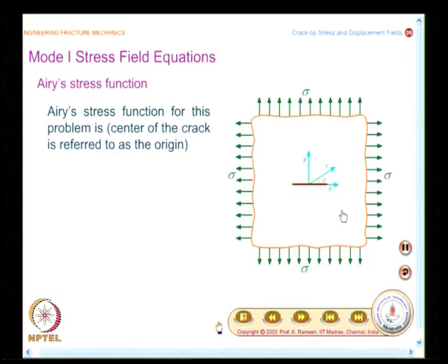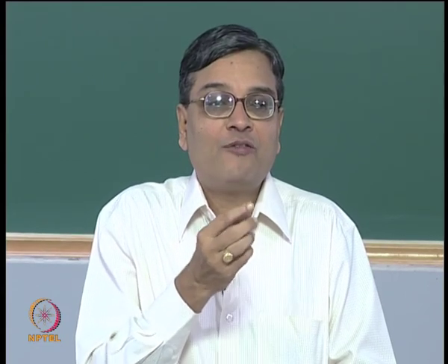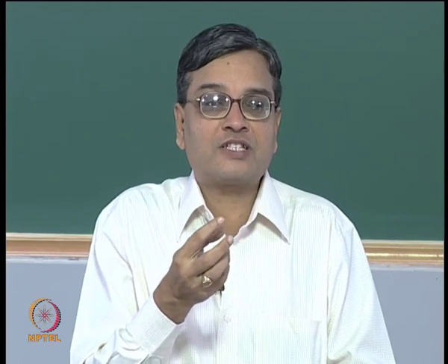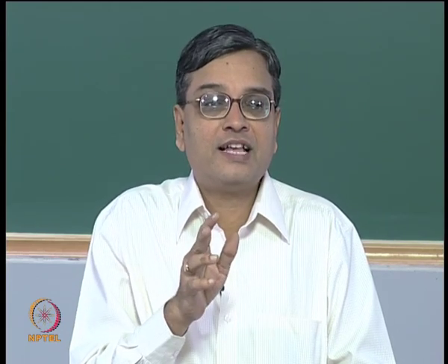But what you find here is that Westergaard has actually considered the problem of a central crack in biaxial loading. Just because people were accustomed to solving these problems for uniaxial loading, rightly or wrongly, whatever solution Westergaard provided, they simply used it for a uniaxial situation.